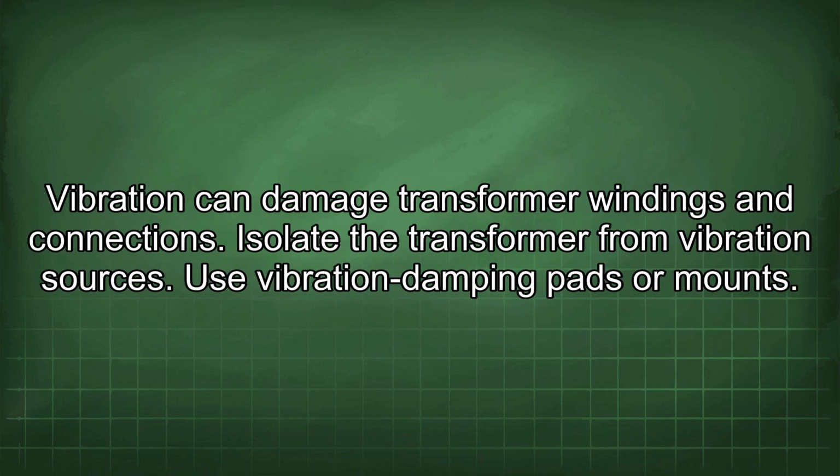Vibration can damage transformer windings and connections. Isolate the transformer from vibration sources. Use vibration damping pads or mounts.